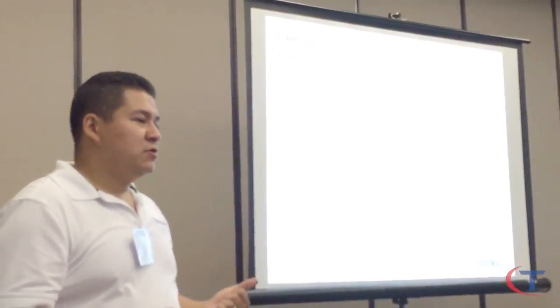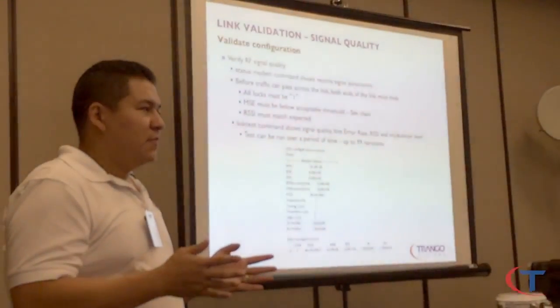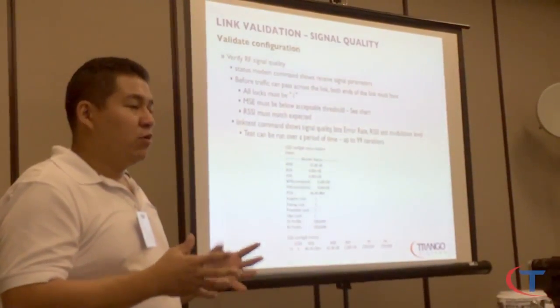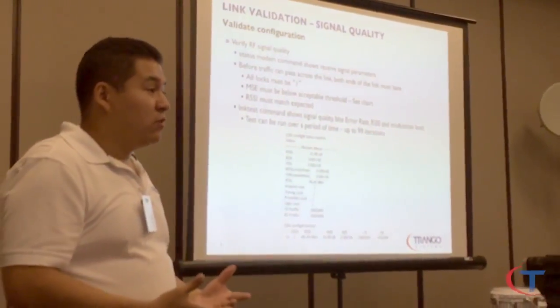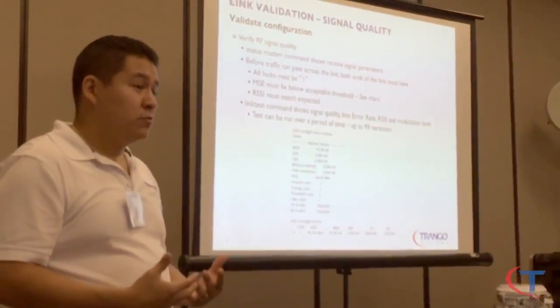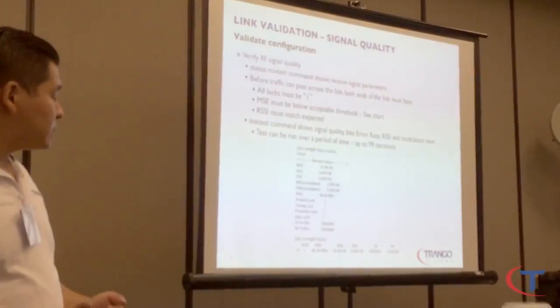So when you have BERs, it's not necessarily an equipment problem. It may be interference as well, somebody transmitting really close to you. That's also a possibility.